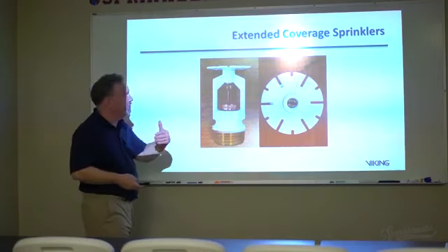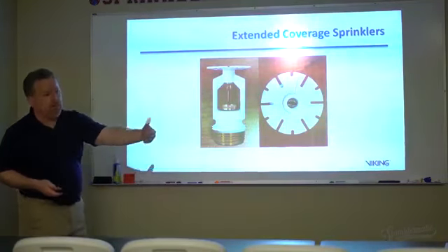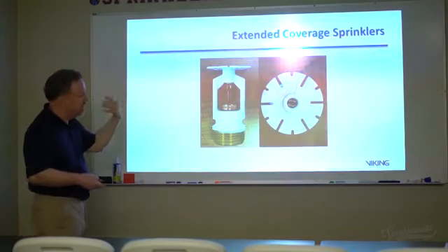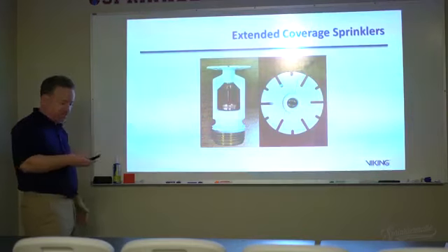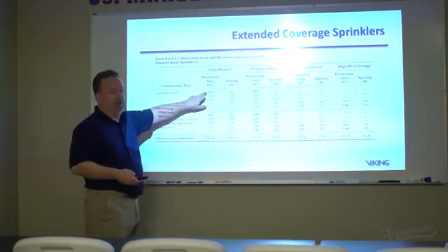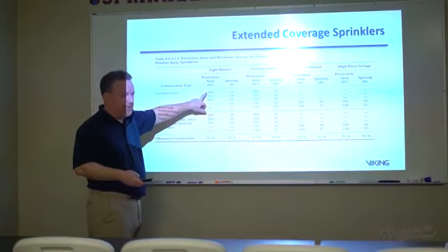Okay, extended coverage sprinklers. All right, so moving on, now back to basically upright and pendent sprinklers, and this particular section also addresses extended coverage sidewalls, all the way up to 20 by 20 spacing you can do.